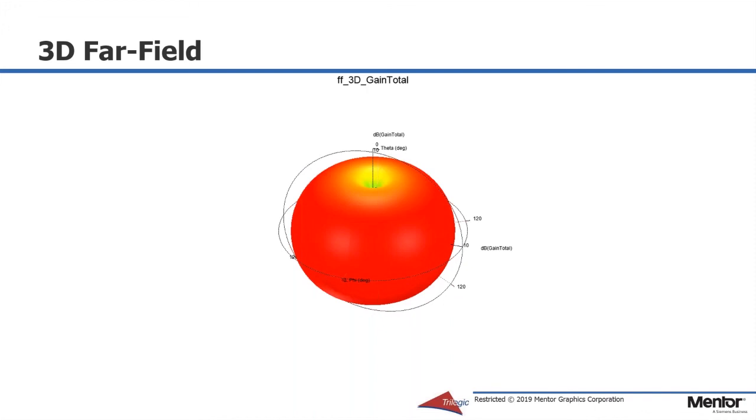Sometimes, just to give you an example, we have developers that would like to use polycarbonate instead of ABS as a material. Radio waves don't go as easily through polycarbonate, as strong as it might be, and as resistant as it is to scuffing and to dropping. ABS lets radio waves go through quite a bit more easily, and polycarbonate is another source of loss. So here, again, in this 3D far field rendering, we can see the null right here, and there's one on the opposite side.